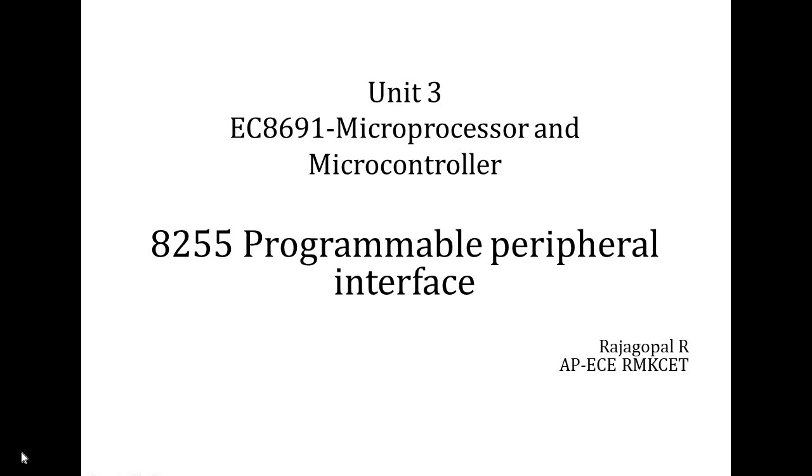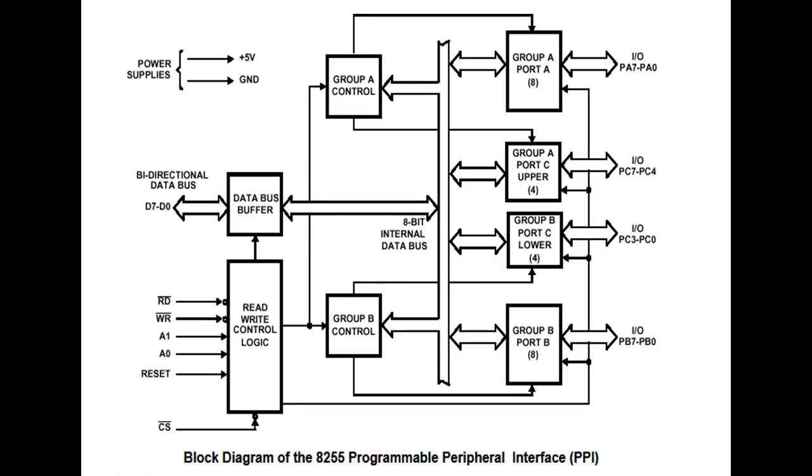Nowadays we don't see any parallel devices in the market literally, and this is mainly used in system design because the microprocessor receives and sends data parallelly. So this interface is mainly used in system design to connect many other parallel devices interfaces to be connected with the processor, 8086 in our example. It is also used to connect the parallel devices with other processors too.